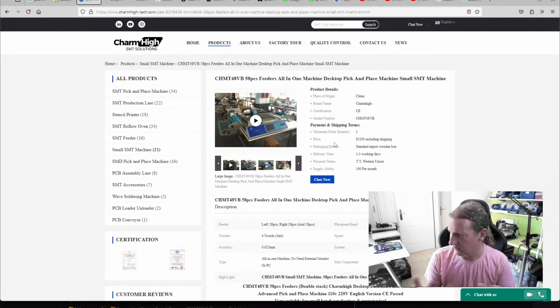So I disassembled the machine and put new cameras in it that I bought 5 years ago, reflashed the control board with SmoothieWare, which is the software that you have to use on it. Took out the touch panel because OpenPnP needs a desktop machine, bought a desktop machine, connected everything up, and started using it. And, well, it left a lot to be desired in a number of areas for me and